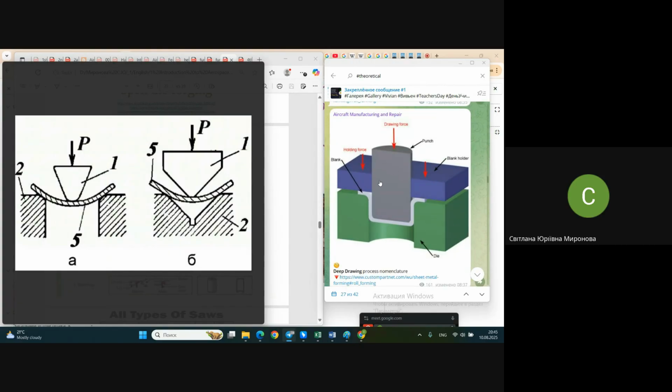Now, let's see on the drawing, for instance. Imagine that you need some other diameter. What does it mean? You need another couple of punch and die block. If the diameter differs even by 1/10 of a millimeter, it's already a problem. Or you have punch and die block which, it's quite clear, have a clearance here which corresponds to the thickness of material.